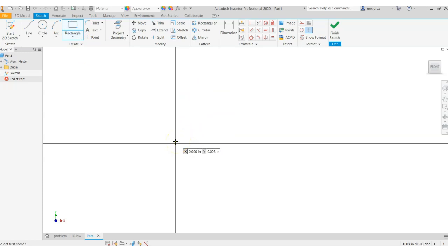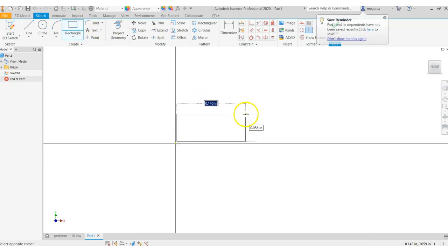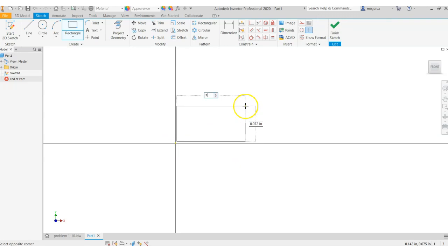For this particular example, if we need to do something symmetrical and make a sphere where we need the origin so that we have an easy mirror plane, then we can do that. Really depends on the part. But for something like this, let's draw a little bit outwards, like right around here. So I'm selecting rectangle, and I want my length up top to be 2. Use your left hand to tab over, and the height is going to be 1.25.